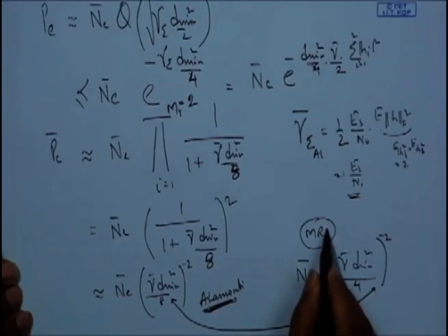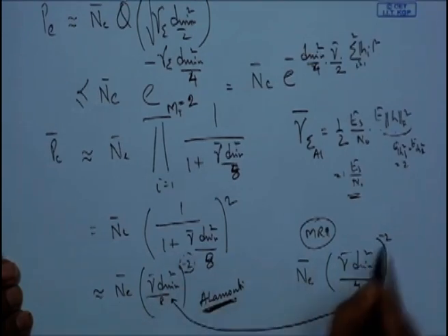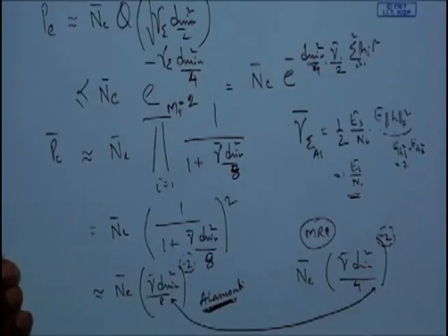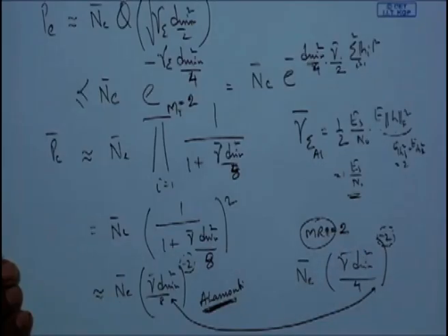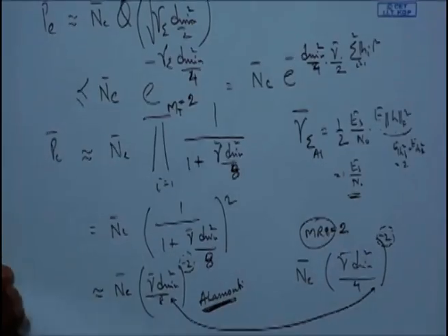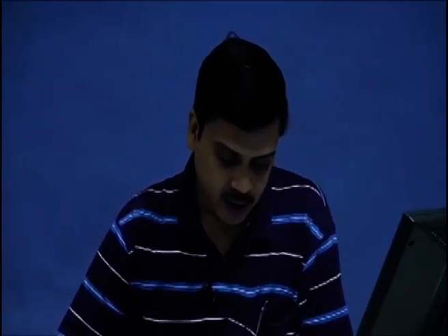So in MRC you can clearly see there is an increase in average SNR compared to the Alamouti scheme, whereas the order of diversity is the same in both of them because they have these 2 branch antennas. So we are comparing MRC when the number of branch antennas is equal to 2 with this case. So if we would look at the error probability curves in this case, we'll get some performance like this.